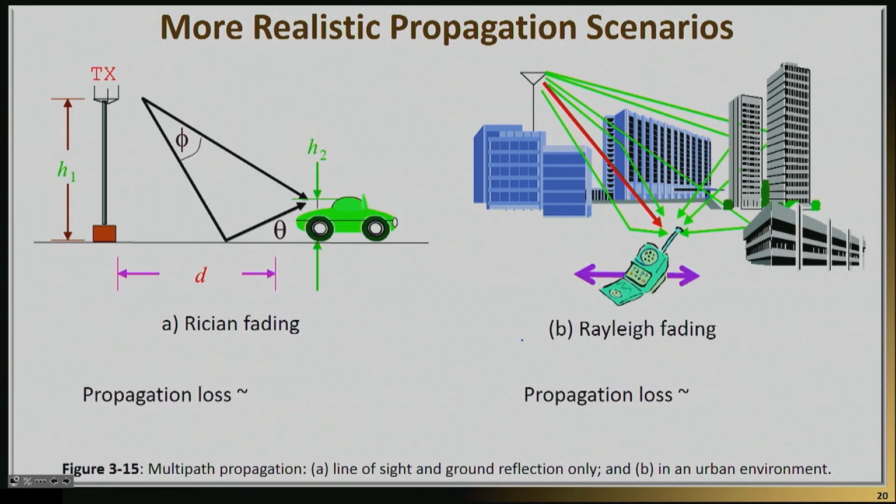There is one example here where you have the direct line of sight communication, but you also have a reflected power that may reach the antenna. In this particular case, this is given by ground reflection. And there are many cases where those two particular beams or other paths are dominant. So if you're driving, for example, your car in an open space, that reflection from the ground and the line of sight path are going to be the main two dominant paths. Of course, you might have reflection from trees or the car itself, but the reality is that you will have two main dominant paths.